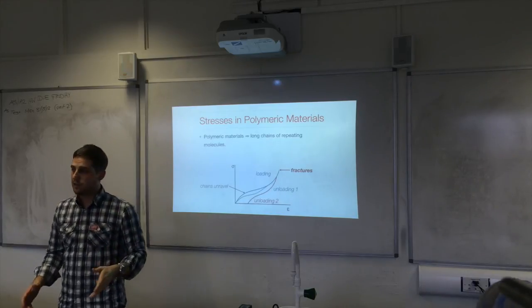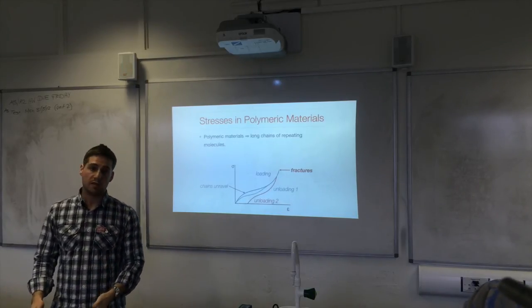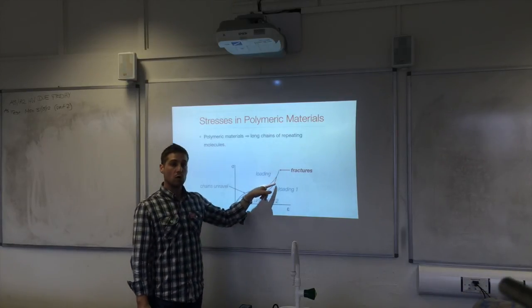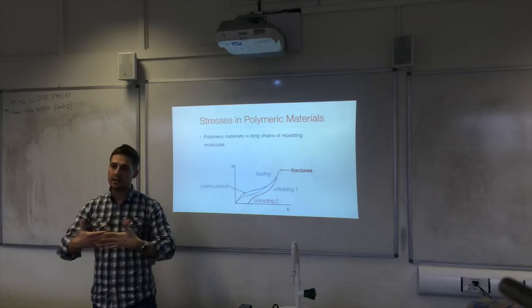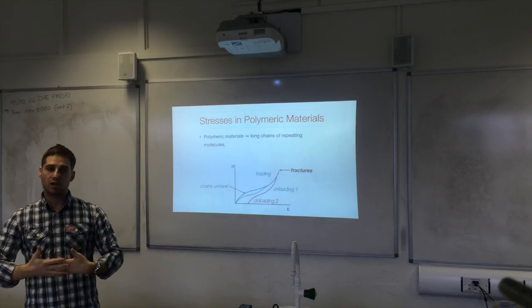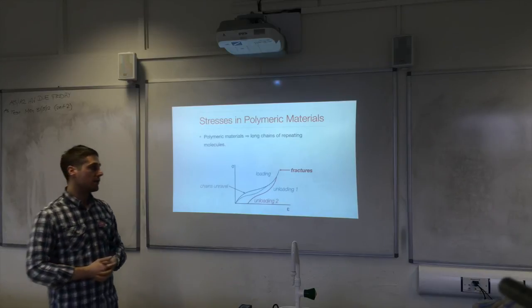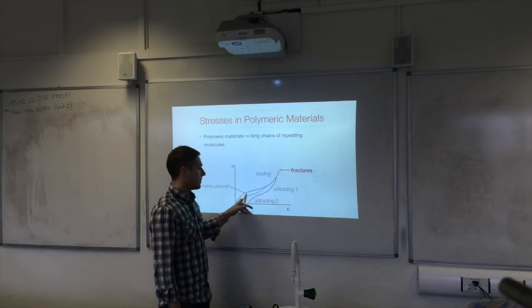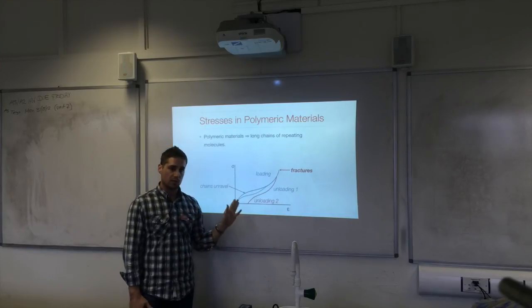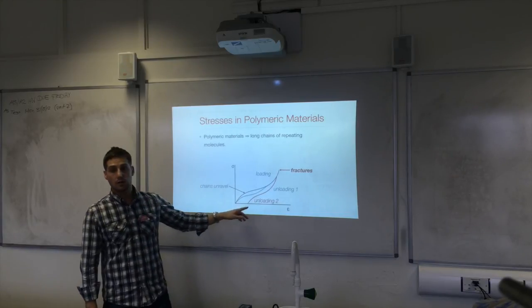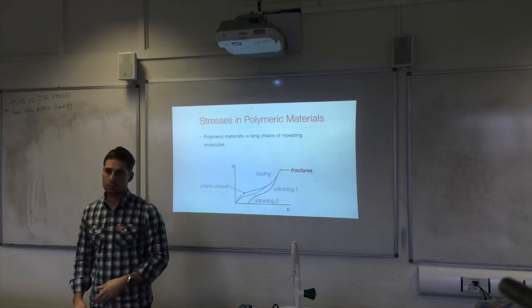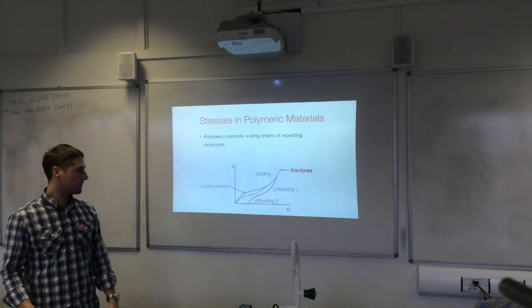Now, in both cases, the area under the graph is different, so therefore the amount of work done loading it was more than unloading it. And the reason for that is the molecules rub against each other, there's friction there, there's heat generated, so you do more work extending it than allowing it to return to its original length, or to return to a permanent deformation state.